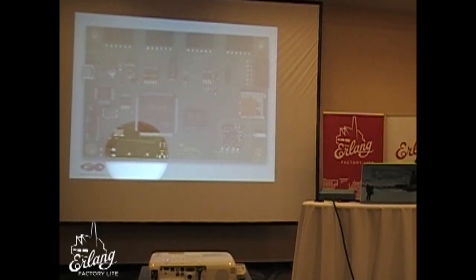So next, we have a bunch of hardware connectors. On the top here, we have PMOD connectors, and it's a standard by Digilent, and it has 80 plus ready-made components you can buy, and you just stick them into these slots, and then you can interface with them directly. And I'll show some more examples of such components. So these ports, we have 2 GPIO ports here in the top. We have one UART port here, and then we have 2 SPI ports.